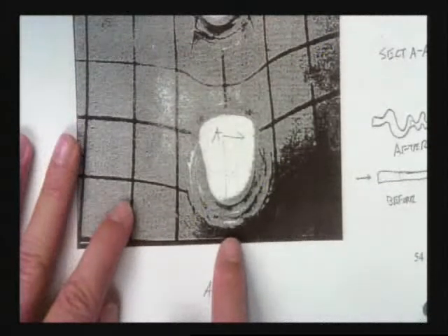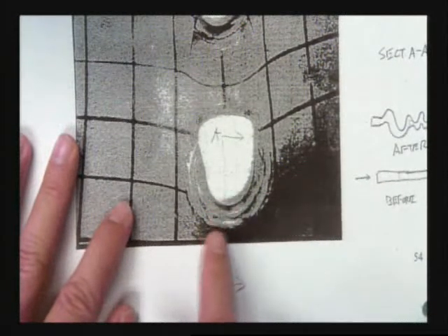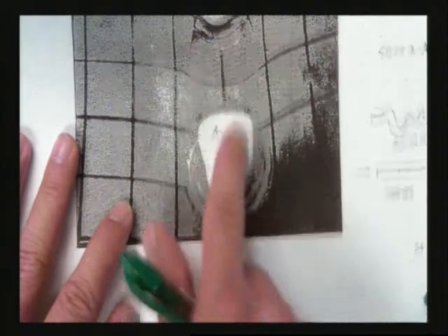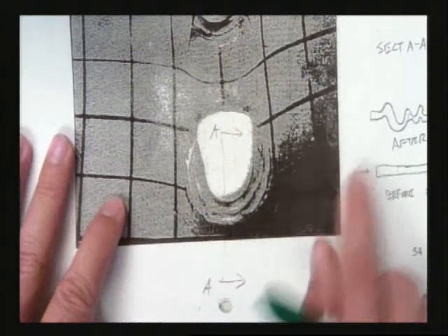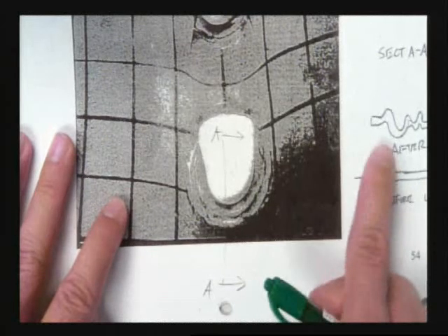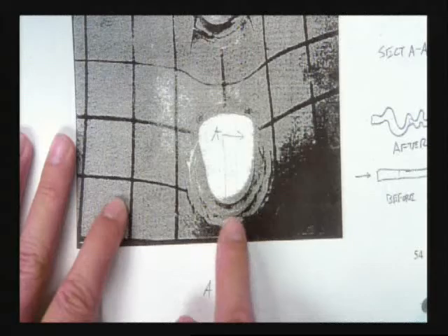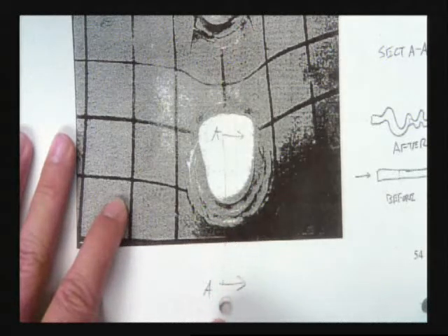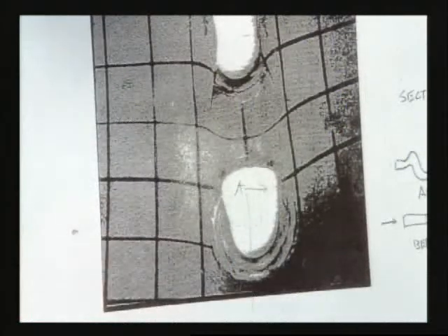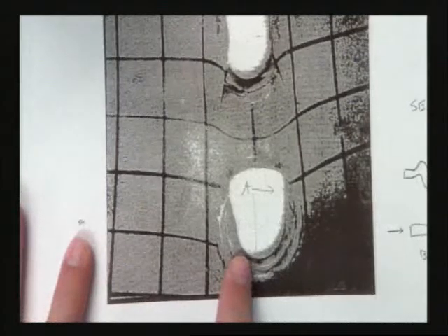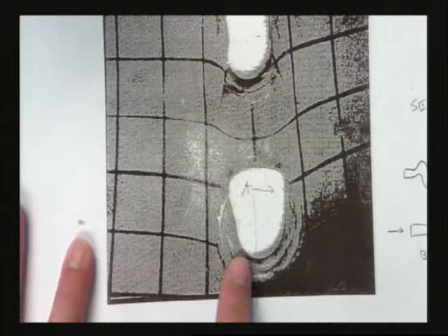Okay? But what bearing looks like when it happens looks something just like this. You see a localized buckling or crushing. If we were to take a cross-section and look at this from the side, this is what it looked like before the load. This is what it looks like after the load. Okay? The bad thing about this is you started out with round holes, and you ended up with slotted holes. That means your connection can lose geometry, can change geometry because of localized crushing at the end. Okay? And that's bad. You don't want that.